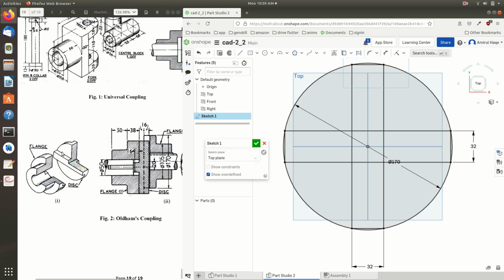And now it would be better to extrude this disc. The disc has 16 into 2, so 32 at the middle, and each rectangular extrusion has again 16 to both sides, so that would be a total of 64. So it's better to extrude all parts by 64.